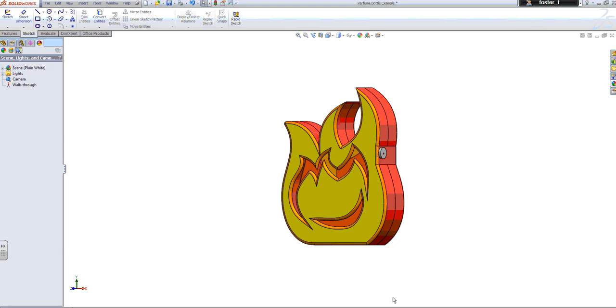Now they're not visible in this view here. You can add them by clicking on the little glasses at the top there and click on the lights, like that. That's adding the lights onto it. Or you can right click on the word lights and show all lights in that way. So there's two different ways.